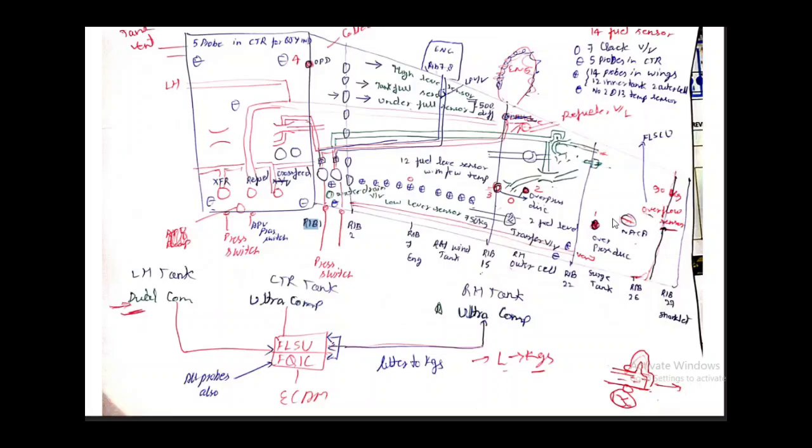Once fuel comes into this surge tank area, there are 3 components: the overflow sensor, the overpressure disc, and the NACA. The overpressure disc can rupture depending on the condition, and the NACA is a flame arrestor, giving positive pressure into the tank.